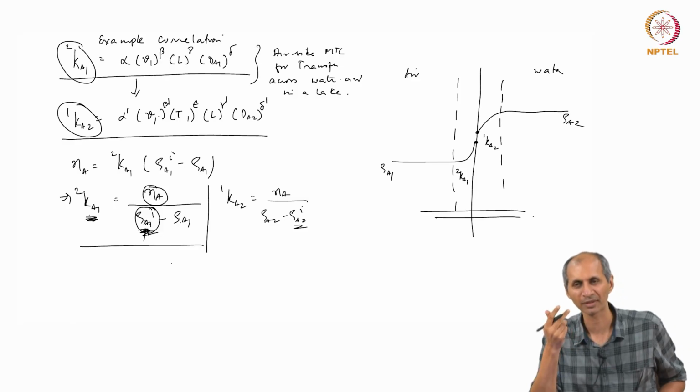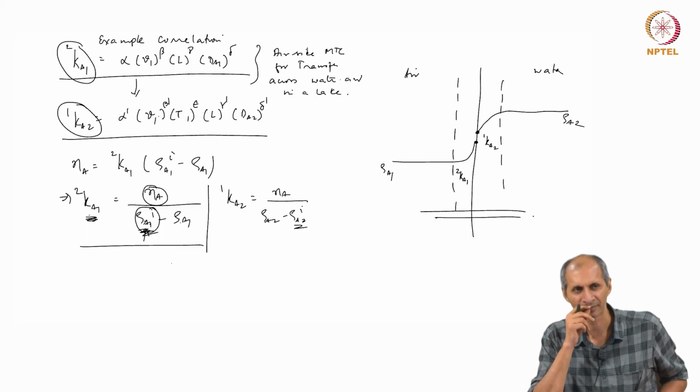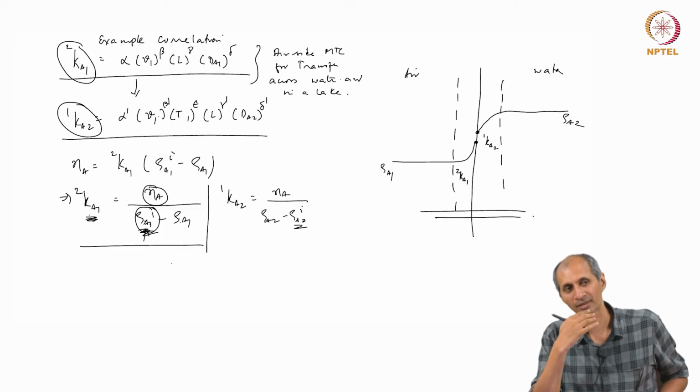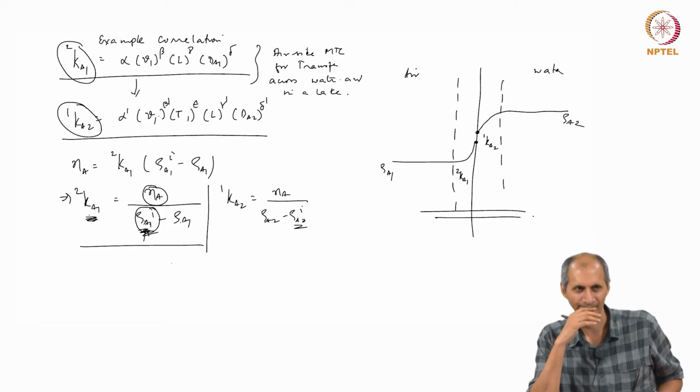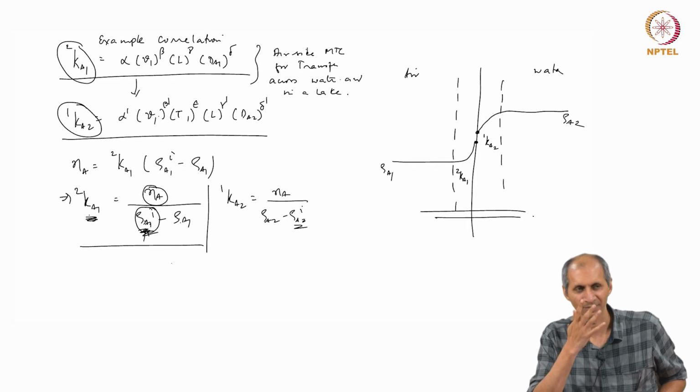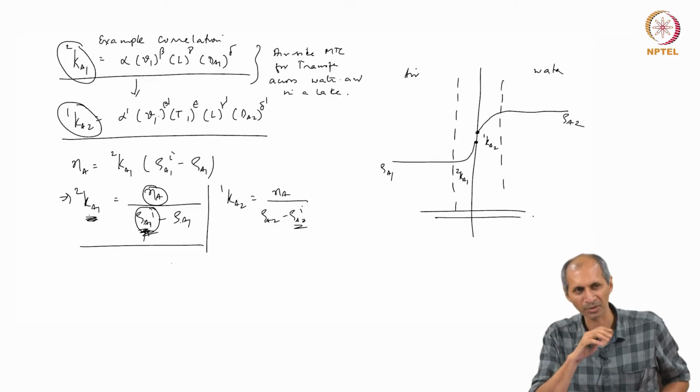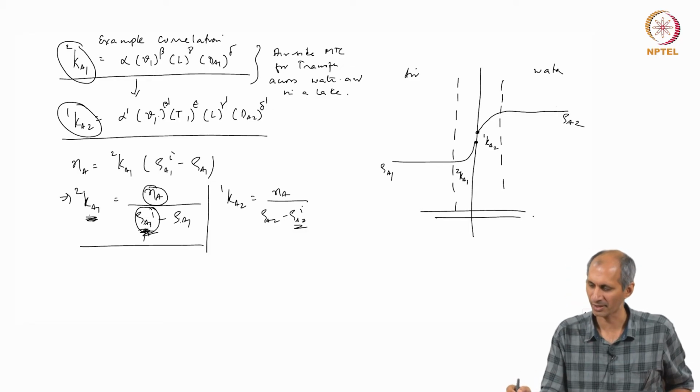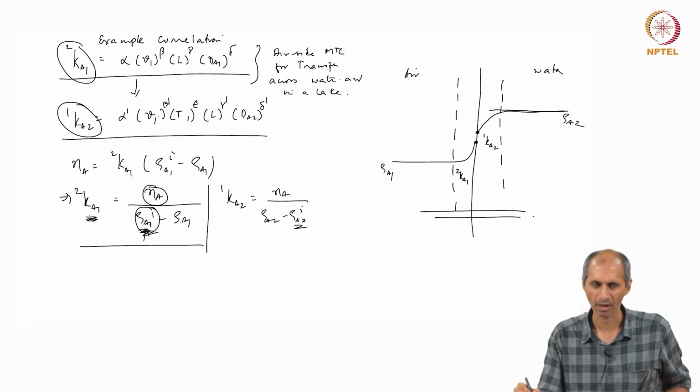Well mixed, but we have already started mixing it. We will still get a small region. What is the maximum limit of the well mixed condition? By saying well mixed, we are saying uniform concentration throughout, all the way to the interface. Is there any case where this will absolutely be true? In other words, is there any condition by which this becomes a straight line going all the way to the interface?